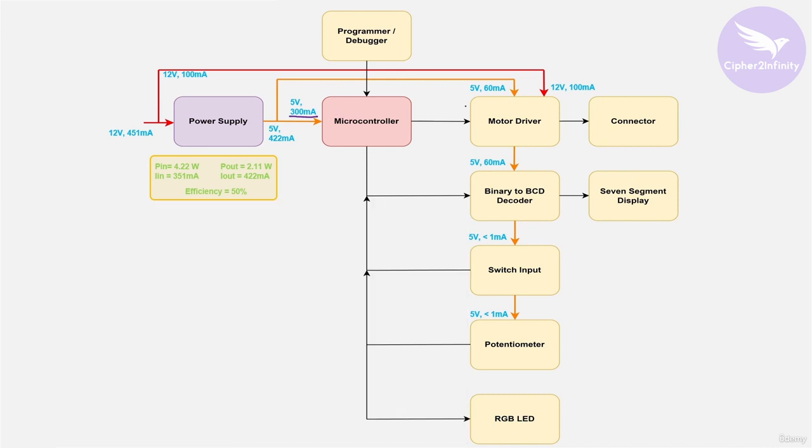So in the same way, for different blocks you have to refer to the datasheet of the ICs, and in the electrical characteristics section of their respective datasheet, you will find what maximum amount of current those ICs are draining.